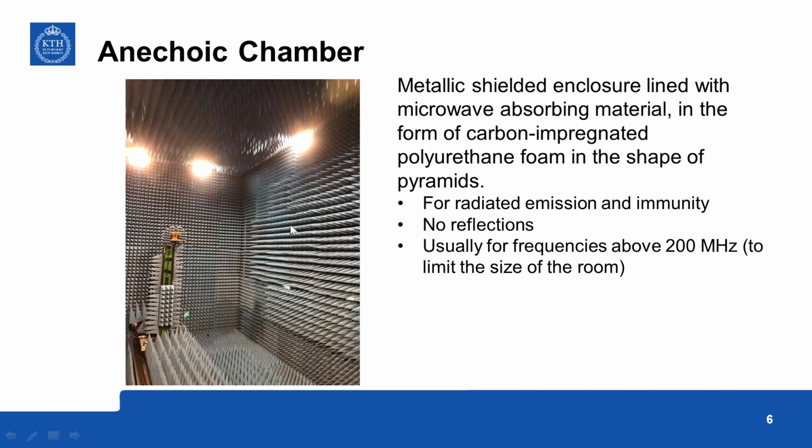So basically you have a shielded enclosure on the outside, and this shield will prevent other electromagnetic fields from entering into the test area. So you are blocking out all the external fields. Then the cones, the microwave absorbing materials, will make sure that there are no reflections.